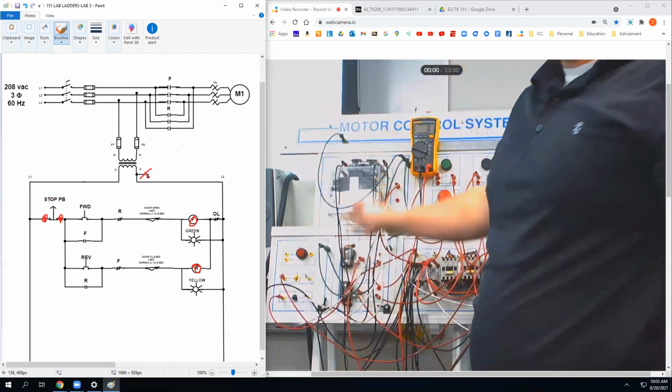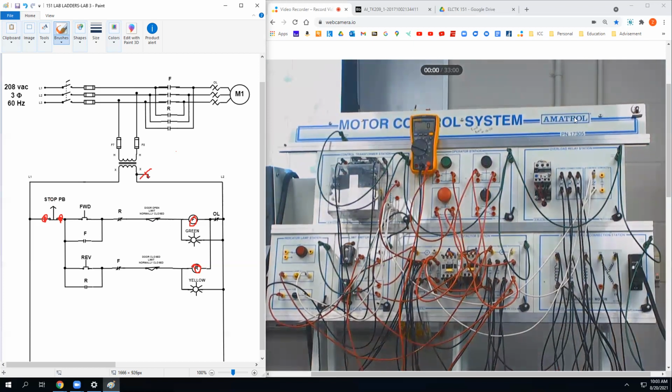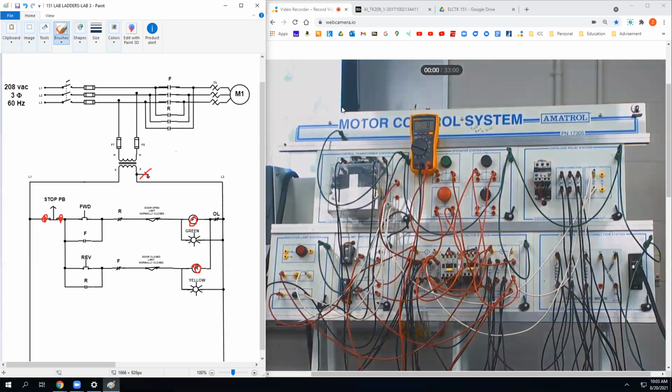So then you're okay to pull that thing off and replace it. The whole unit, or do you replace just the individual coil? It depends on the transformer, but especially for something that small, it's probably more cost effective to just replace the whole thing. I assume since those aren't really fixed, we just throw the whole thing out. Most transformers probably don't even have the ability to rewind them because they're molded cased. But if there's a really big, really expensive one, it might be cheaper to have somebody rewind it than to just replace it.